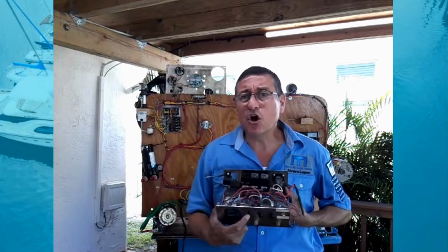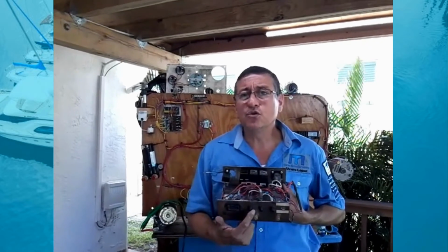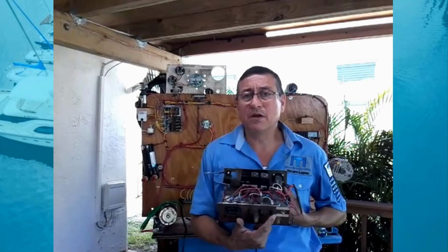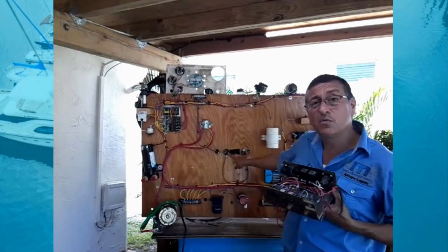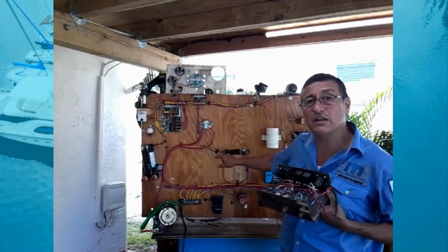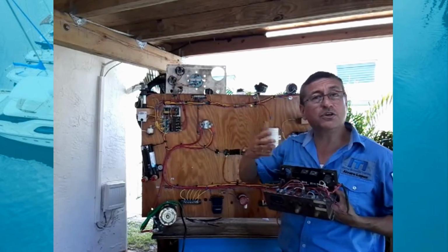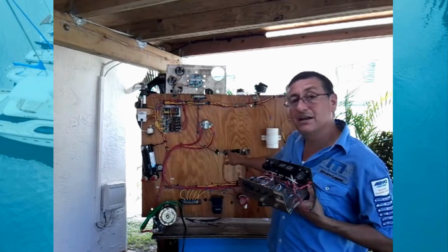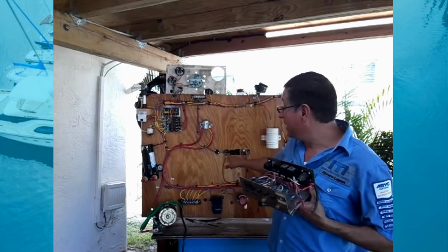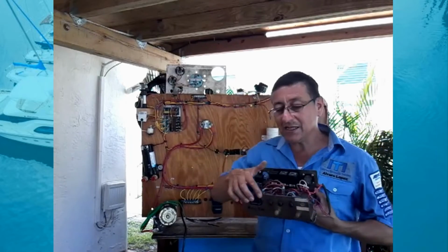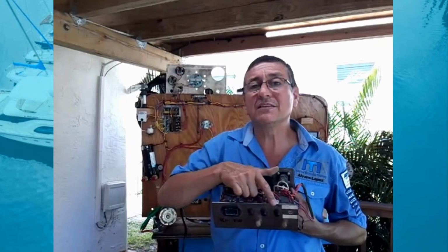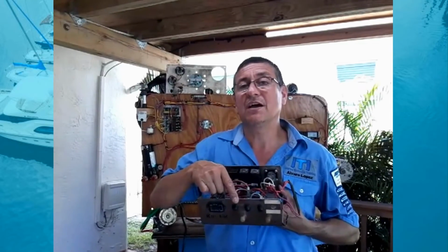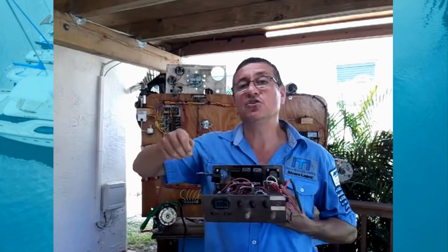Can I replace those switches, start, run, and stop, for this type of switch with 3 positions: battery, ignition, and start? The typical ignition switch, yes. The battery is the start, the ignition is the run, and this is the start. It's exactly the same. You can replace those normally open switches with the typical ignition switch.